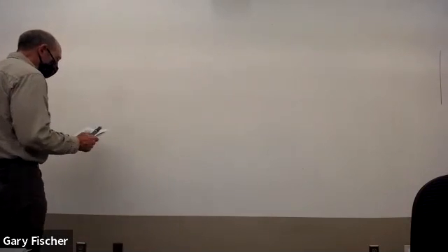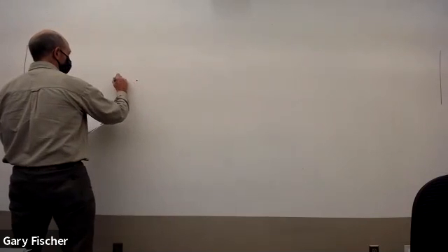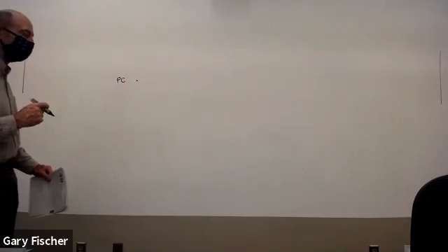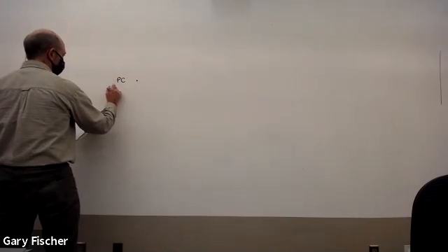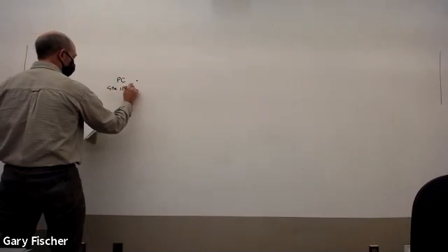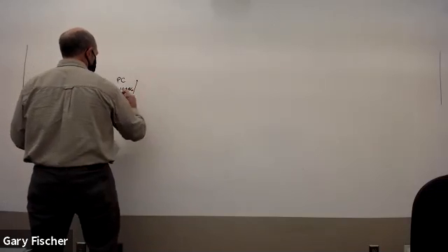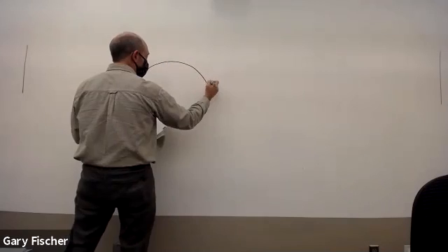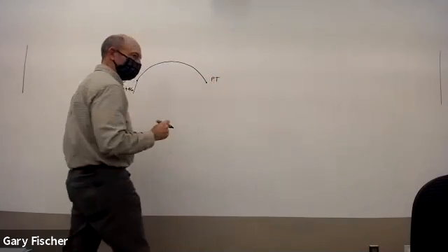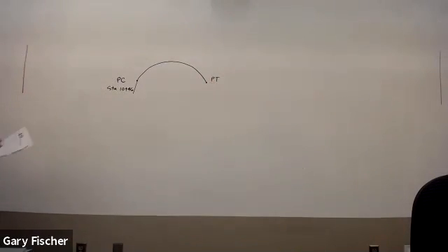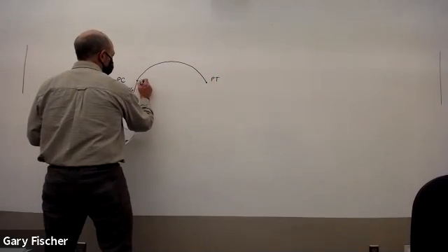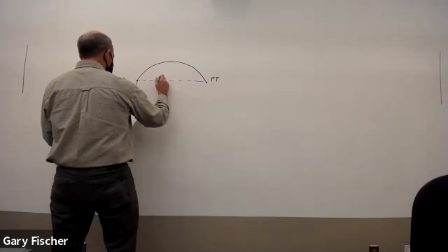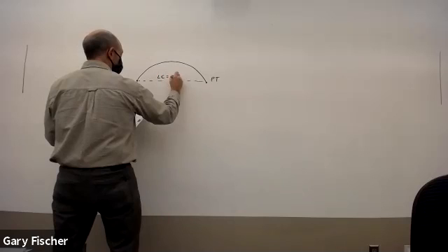All right, so on number 1, here's what they give you. They have a curve, and if you know the terminology, it helps quite a bit. They give you what's called a PC, which is what, Ashley? Point of curvature? And they give you a station at which that occurs, 10 plus 46. So we've got this line coming up and it hits that point. That's when the curve starts, and then it goes through this curve and ends up at a point they call PT, the point of tangent. They give you the length of the curve, 820 feet.